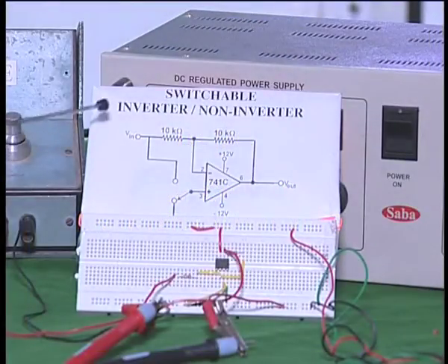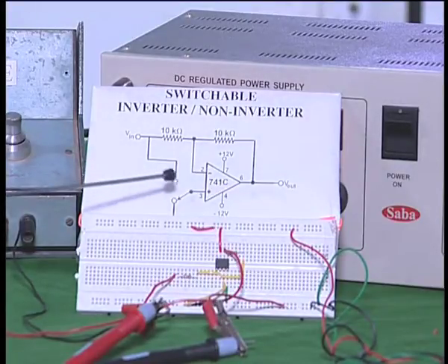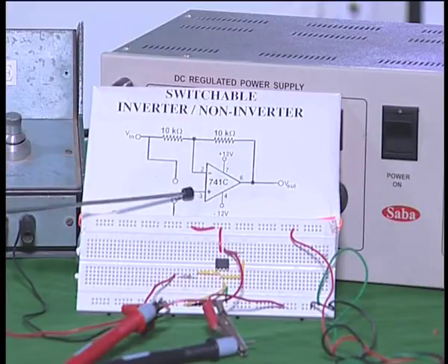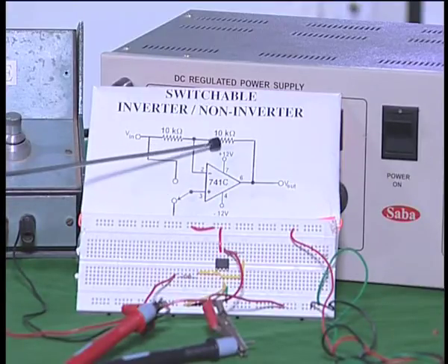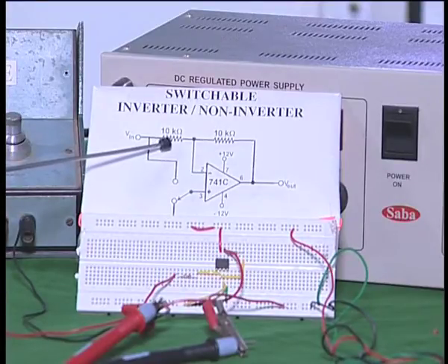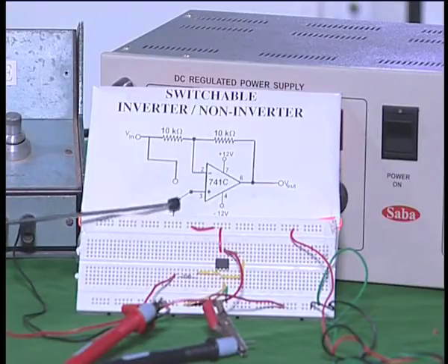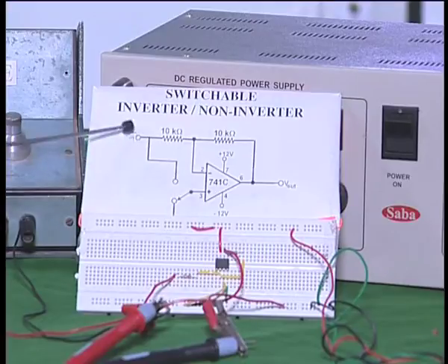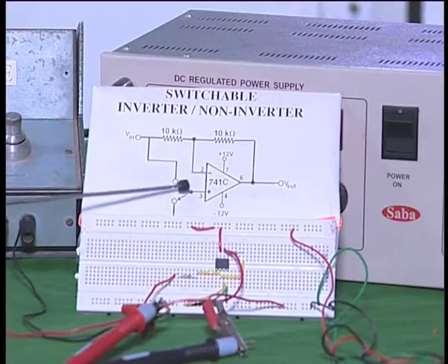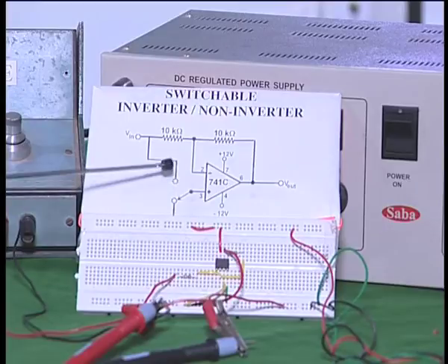I want you to see the circuit here. It is the same as the one which I showed you just a couple of minutes ago. So, you can see there is an operational amplifier 741 at the center. There are 2 resistors which are called R and R in our circuit. This is 10 kilo ohms, this is also 10 kilo ohms, and you see here that the non-inverting input can be either connected to the ground or connected to the V in input by using this switch. Instead of the switch, I am going to use a wire which can be connected either to this end or this end. That is the only difference.